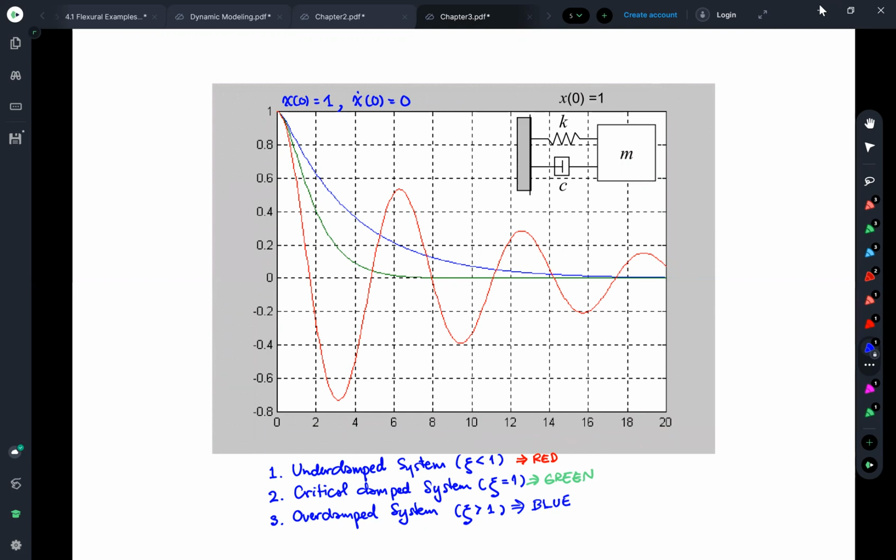Damping is good to us. We need more and more damping in our system. But it doesn't tell us that the overdamp system has more damping, so some of you may feel the vibration should stop faster. We should not say so.